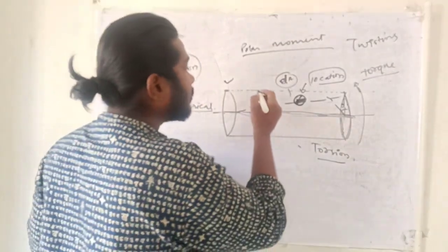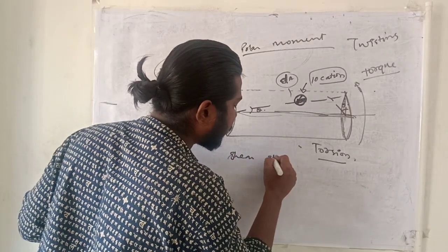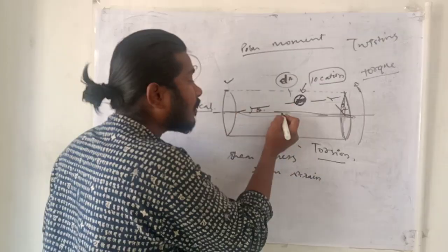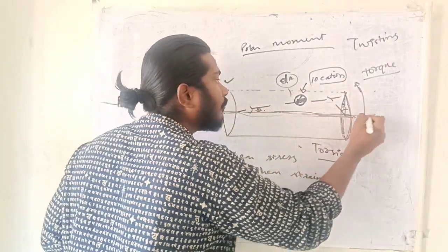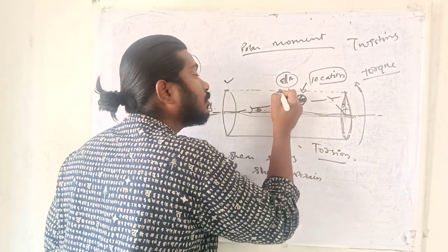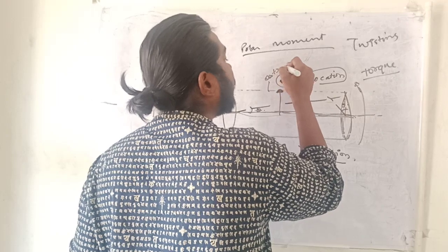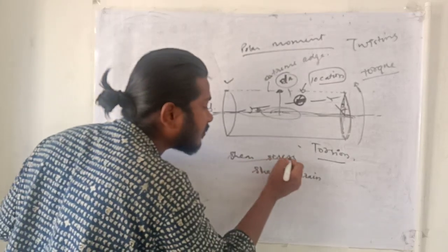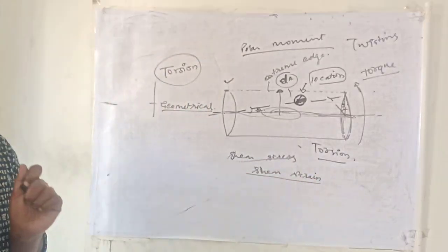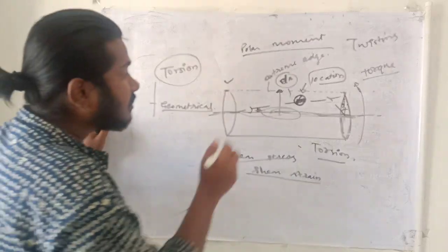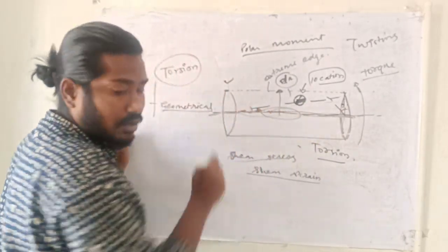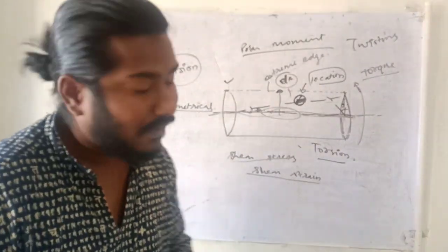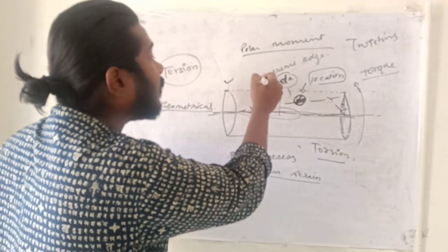Now shear stress or the shear strain increases from the center of the neutral axis to the extreme edge. It means at the center, the minimum shear stress or the minimum shear strain can be witnessed, while at the edge the maximum is going to be seen.